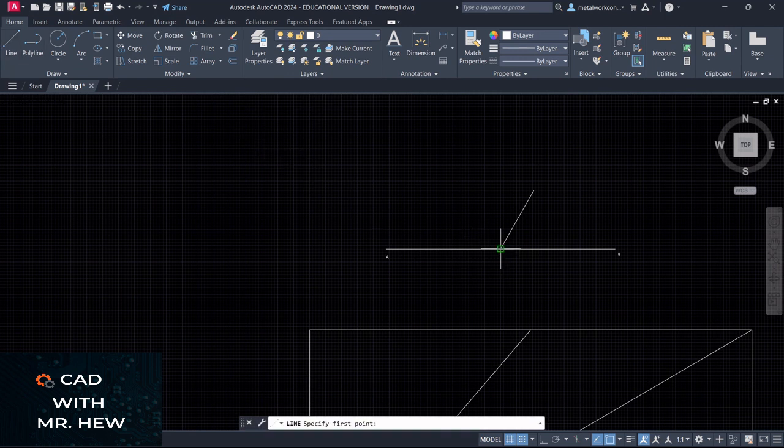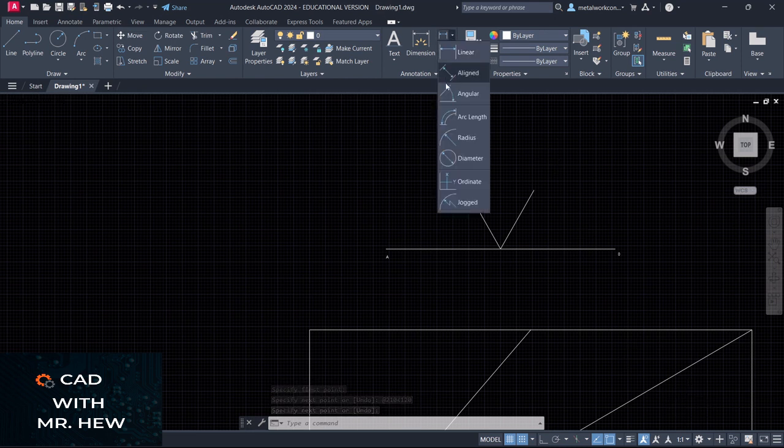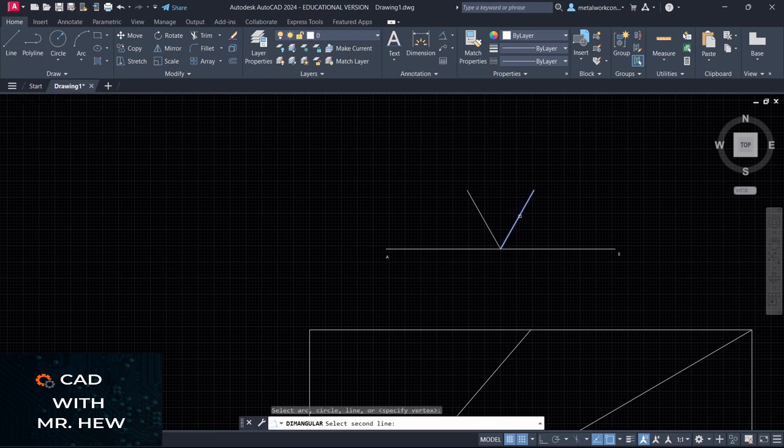Line, this intersection, we're going to type at, relative to that point, we're going to draw another line 110 millimeters long, less than sign. Gonna put it at 120 degrees, and guess where I think it would be on the other side. Enter. All right. So let me indicate the angle for you and show you that the 60 is measuring from here.